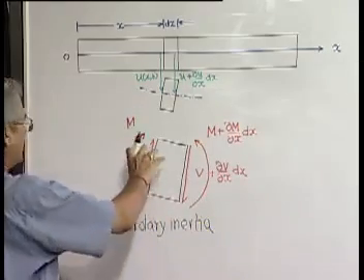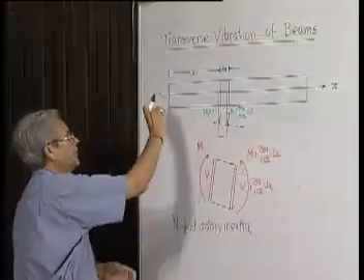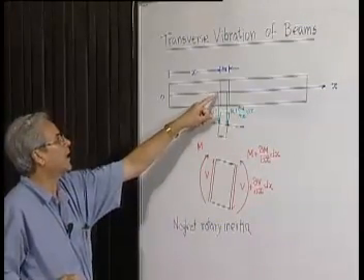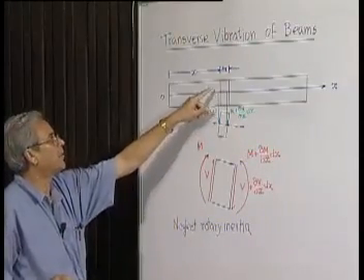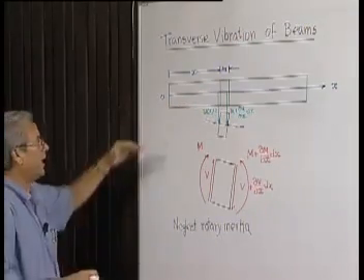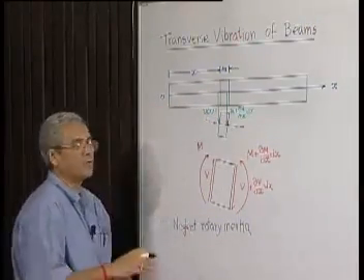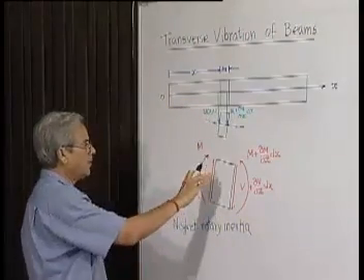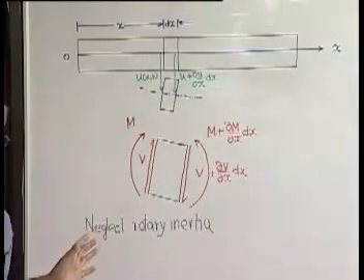It means that, first of all, it is small vibration. So this u is very small, it hardly moves too much away from the original location, and the slope of the bending etc. are all very small. So therefore the angular motion of the element is ignored.